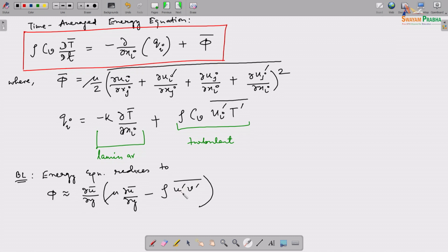And again, we also take the time average of the fluctuating part, which is u dash and v dash. Okay. And where has the third component disappeared? Well, it hasn't, because we are saying that as we go in the z direction, the picture remains the same, it's not changing. That's for us, as the person conducting the analysis, to decide, depending on what we are going to be able to consider. So we consider that it is not changing in that direction, simply as that.